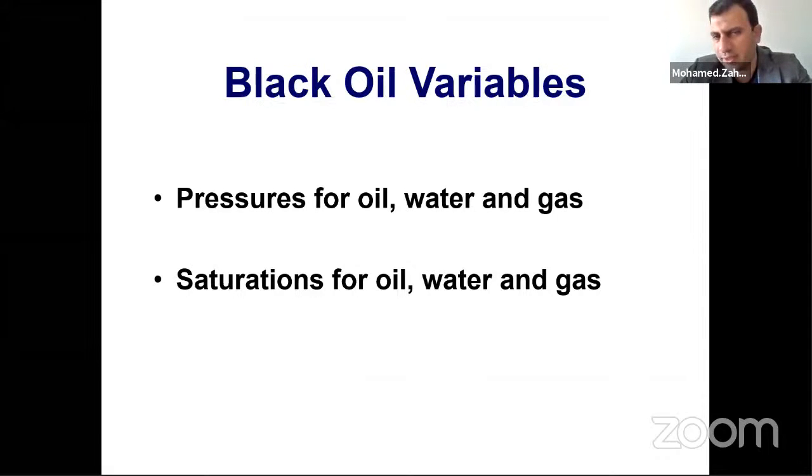You don't have change in saturation, because how will saturation change if the permeability is zero? And if the saturation doesn't change, the pressure will not change. This is something I will show later in the practical. So we don't calculate this equation in shale, just in the rest to solve the change. This is the next slide now.